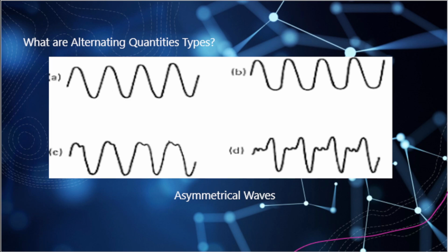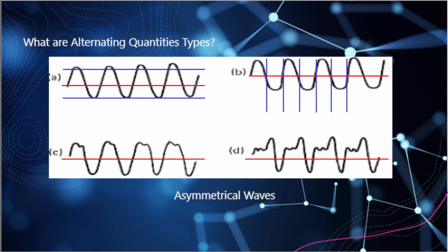And how do we know that they're asymmetrical? Well, if we were to put them onto an oscilloscope and graph them over time, we would be able to determine, such as with item A, that the amplitude starts to shift upward. See that shift above the graticule? Top graticule going upwards, below one going up, more north. So we could say that this sine wave is asymmetrical because its amplitude is asymmetrical in relation to its center, or absolute zero voltage, the point in which the voltage is at a null.